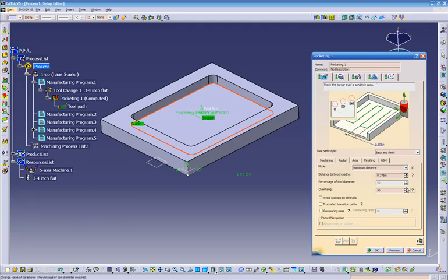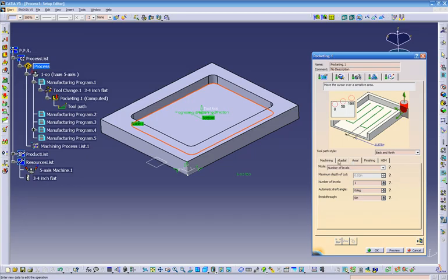They show you right here the difference. But I like ratio the best, 50% of the tool. Then we have radial going sideways, as you see. Axial goes up and down. So it's asking us how many depth of cuts do we want. So just click on this and it will tell you 1, 2, 3, 4.